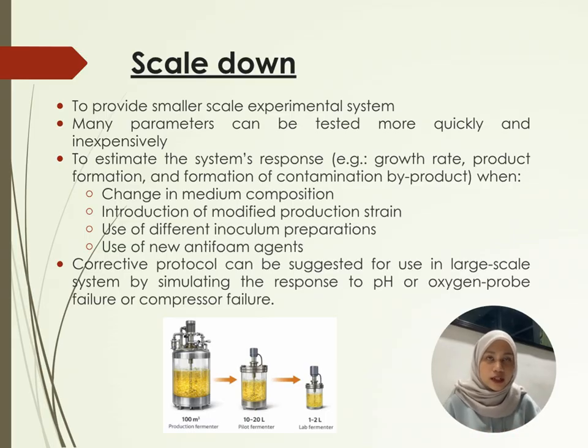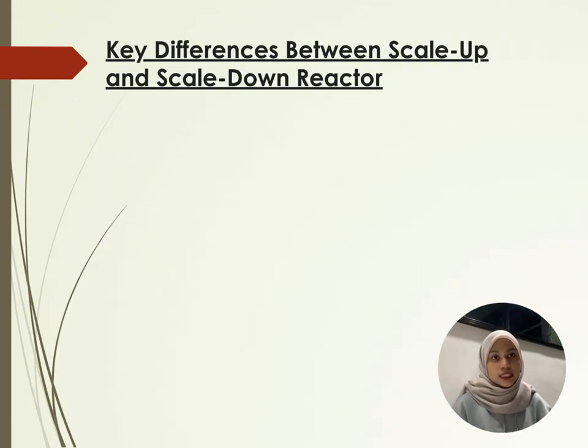Besides that, a scale-down reactor also helps identify problems early, such as pH probe or oxygen supply failure, before applying the process to large-scale production. So overall, it is a practical and efficient system for process development. Next are the key differences between scale-up and scale-down reactors. This table compares both reactors.